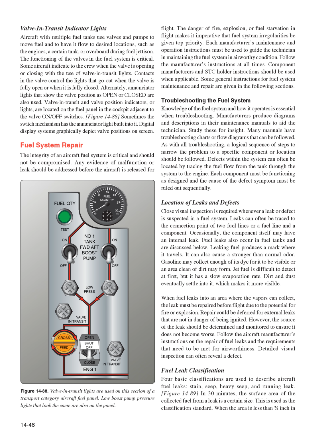Troubleshooting the fuel system. Knowledge of the fuel system and how it operates is essential when troubleshooting. Manufacturers produce diagrams and descriptions in their maintenance manuals to aid the technician. Study these for insight. Many manuals have troubleshooting charts or flow diagrams that can be followed.